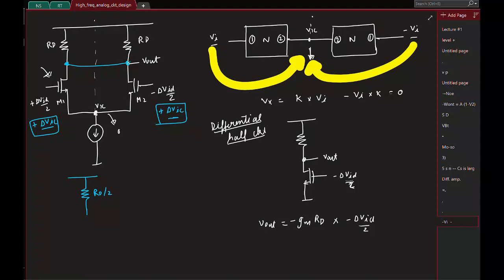and what you see, you have this transistor M1 and M2. Their gates are already at the same potential, sources at the same potential, and I am saying we can also short the drain now. So it looks like the two transistors are put in parallel. So it's going to look like this.